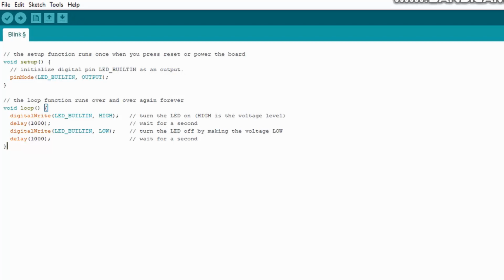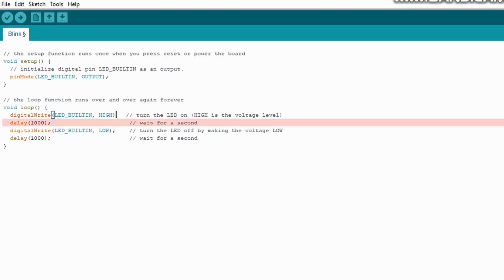And then the delay, it waits for a second, and then after this program right here is done, it starts over because this is a loop. So it'll loop this entire program here. It won't loop just one part of it, it'll loop the entire thing. Then it starts again, and it'll just repeat over and over. And if you look here, you will see the punctuation marks. You can see here that if you delete this piece right here, you will get an error. So you need to make sure you have those at the end of every line.